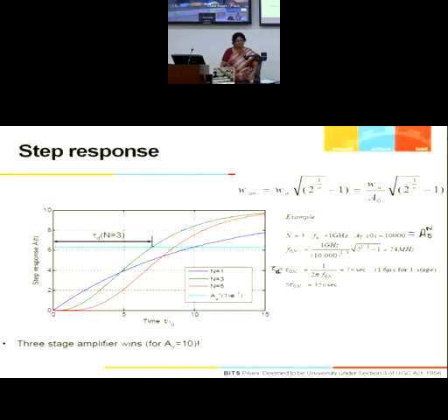So this is the same as what we get in logical effort. Remember, choosing too many stages causes your delay to increase. Choosing too few stages also causes your delay to increase. So we have a minima somewhere in between.